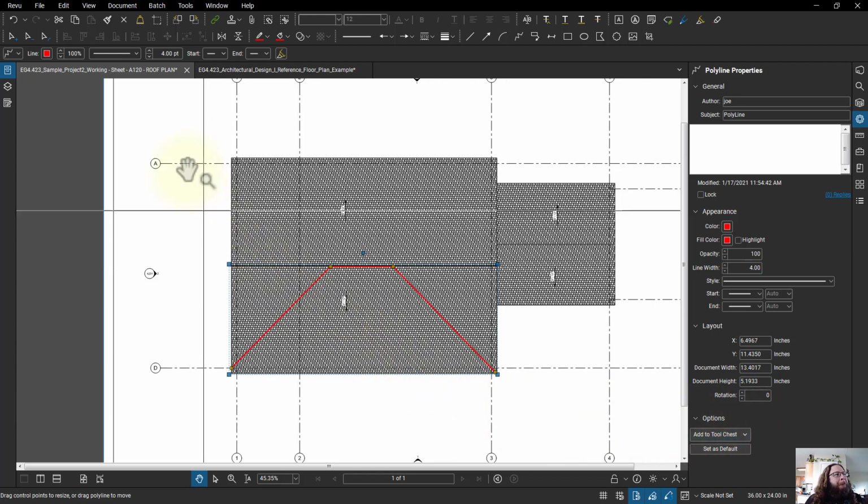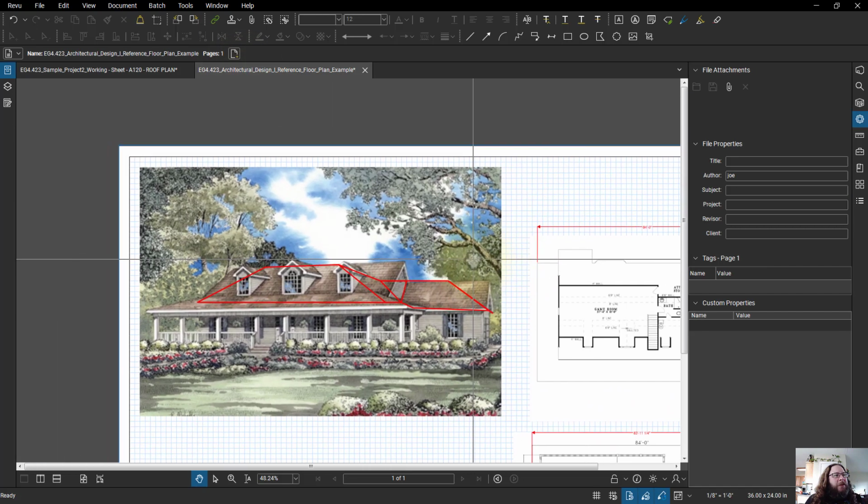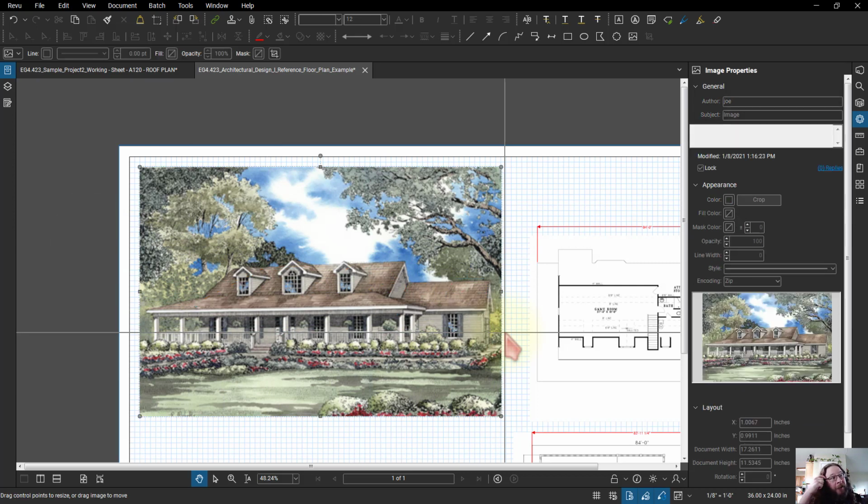So what I want is based on my reference drawing. I want there to be gabled ends. So right now it gave a hip roof, which is from each corner it goes up whatever your slope is and then ties into the next ridge of the roof. But you can see on this photo that they actually have gabled ends here, which just means the roof slope goes up and comes back down on the other side, and it does not angle the roof.